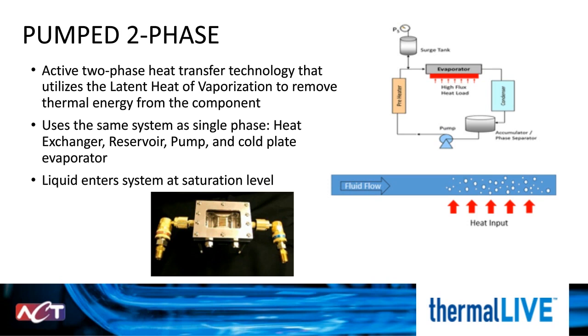And just like the typical single-phase solution, a pumped two-phase system includes the heat exchanger, reservoir, pump, and cold plate. There's one main difference. In a pumped two-phase system, the liquid enters at saturation level. It will therefore vaporize at the controlled desired temperature.